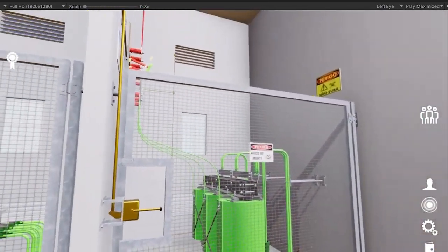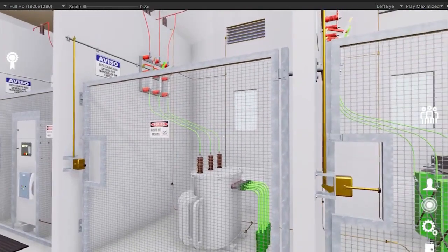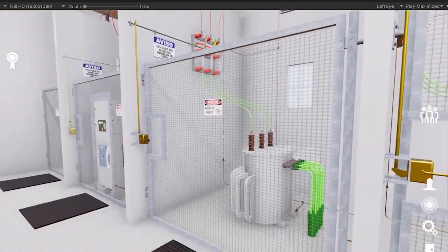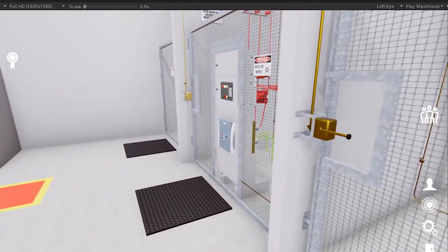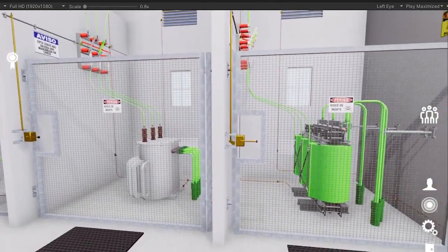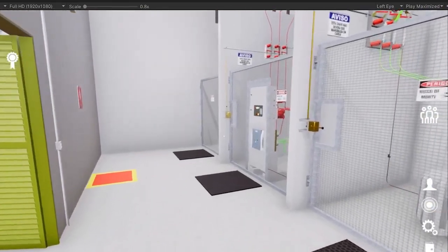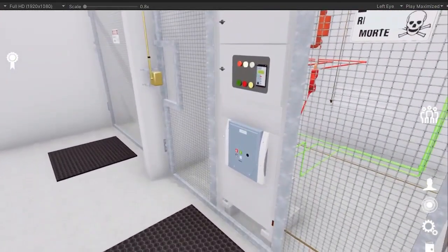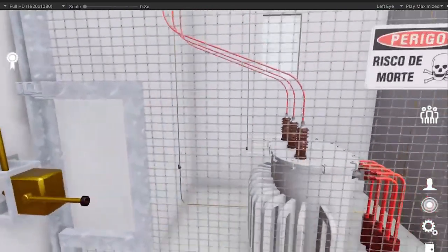it also, it was open. So with both switches it can't work. So I'm going to open my circuit breaker, go back and close this switch here. They weren't in parallel, the two transformers. I'll come here, close my circuit breaker, energized it, listen to the sound of the transformer, and it's energized.